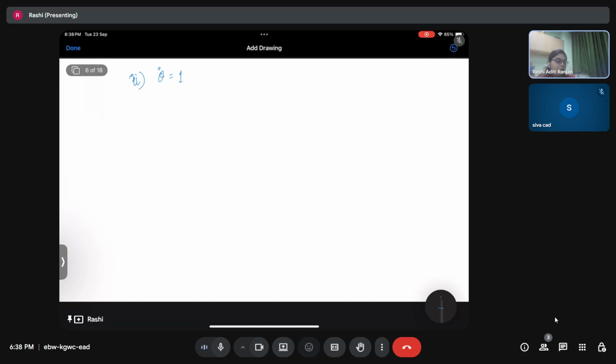We are now giving theta dot as 1. Okay, so if theta dot is 1, now we have, you remember Mij, where j was where our momentum was given and i was the points. So this time it is going to be M12 and M22, because the momentum is given at the second mass point and its effect is seen at 1 and 2. So M12 and M22. So for M12, what is going to happen?